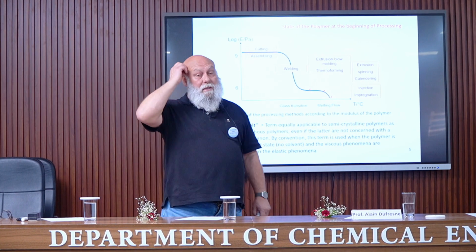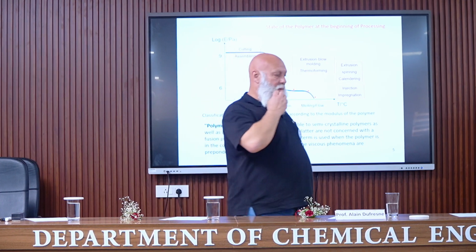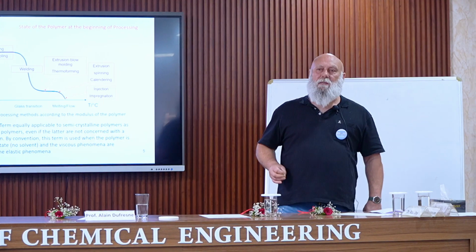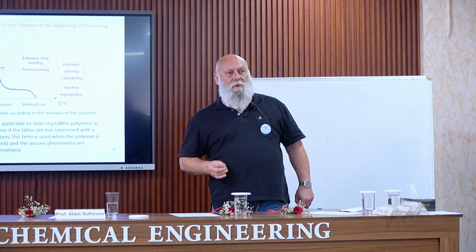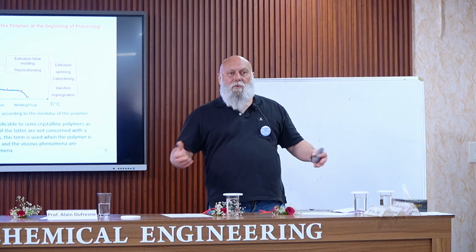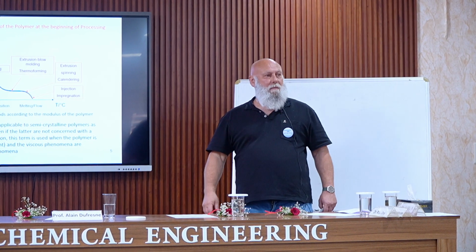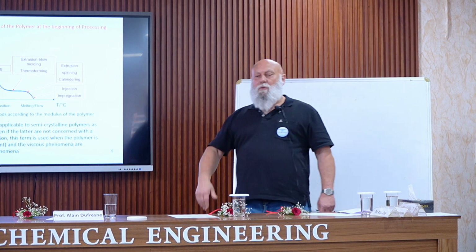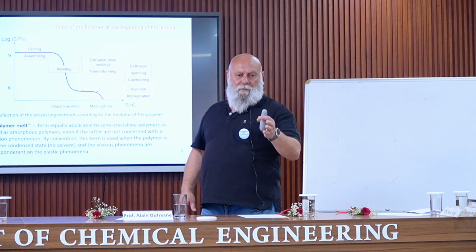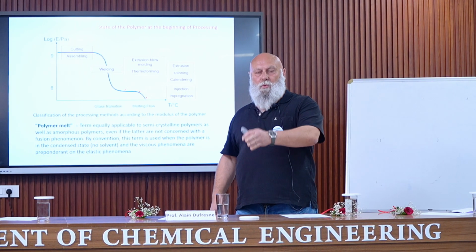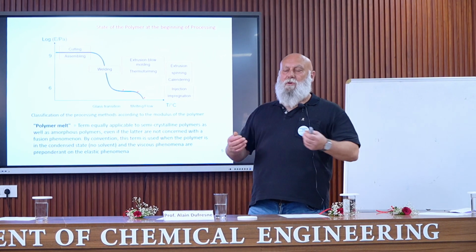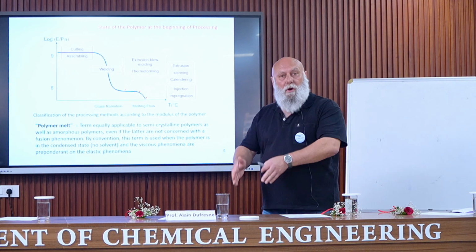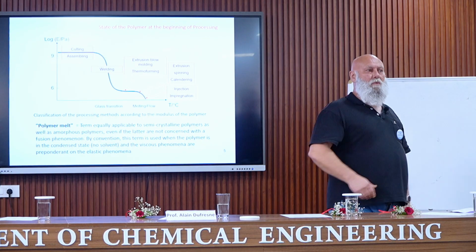Relaxation is a process that corresponds to a difference in the molecular mobility of the macromolecules. Of course, glass transition is associated to a relaxation process, because when the material goes from the glassy state to the rubbery state, the molecular mobility is different. The same for melting and for crystallization.